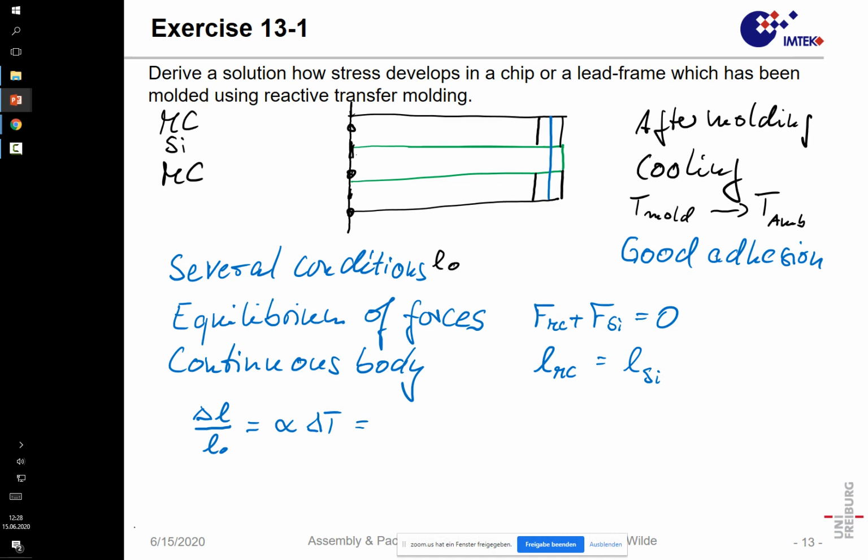Yes, very good. I must admit, in previous years, often there was no one knowing this, so that's a thermal strain. Please note, and that is important, that thermal strain is not elastic strain. It's some different strain. Only if a system is hindered from building up thermal strains, these strains will develop as elastic strains.